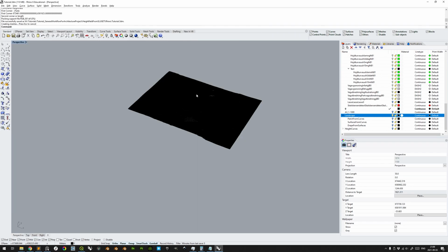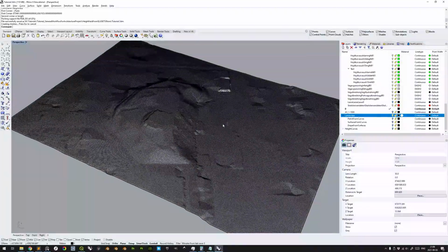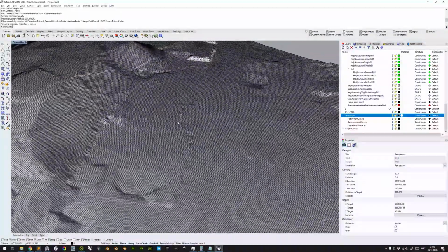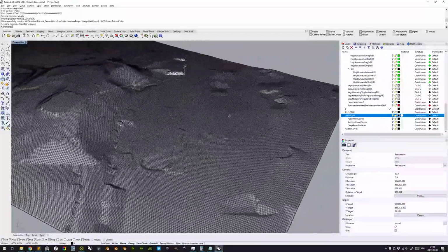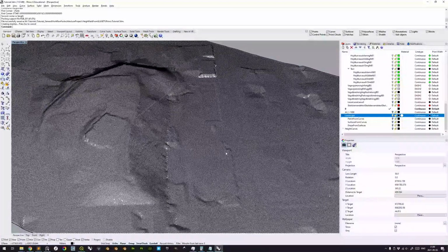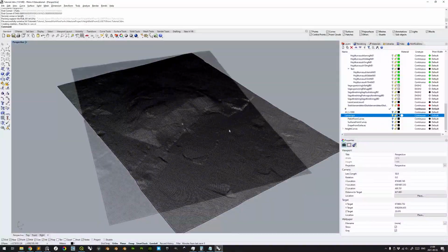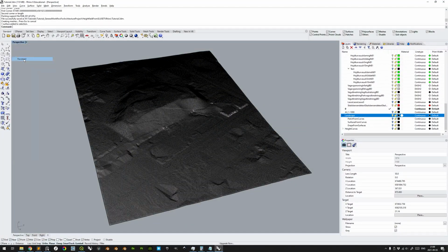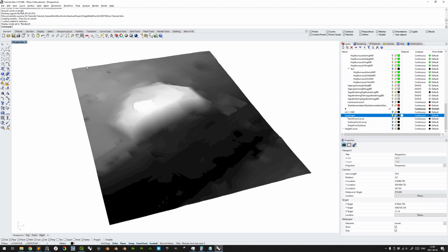Alright, expanding the perspective viewport and moving in, we can see that this is a very high density surface with control curves very tightly distributed, only 1 meter apart. If we change to render display mode, we can see that the grayscale height map is imported also as a color texture. It is interpreted as 8-bit, even though it actually is 16-bit, but since it is rendered as 8-bit as a color texture, not as the basis for the height field itself, it has these gradient errors.